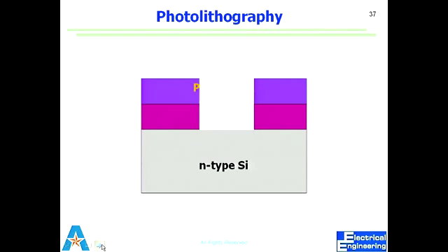What's a very common material we use to remove dried off chemicals? So we have chemicals that dry off. Acids. Water. Acetone, right? Nail polish remover. So chemicals like acetone can remove photoresist. And I don't need the resist because I've transferred that pattern into a hard material, which is silicon dioxide.